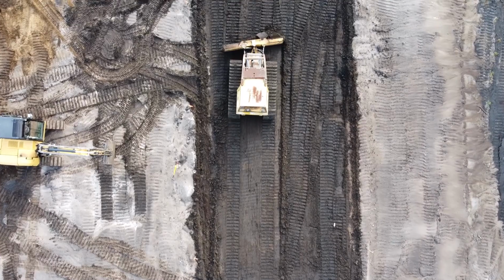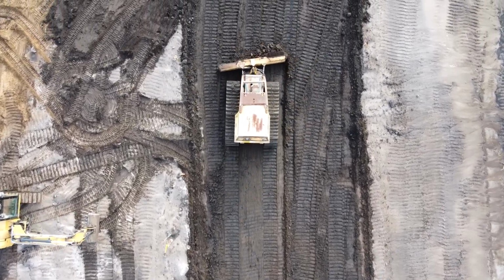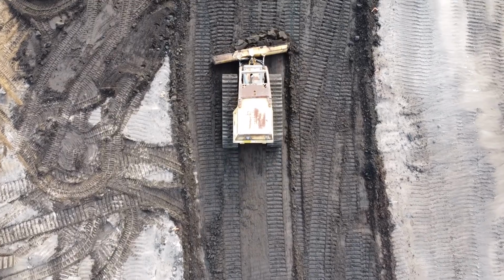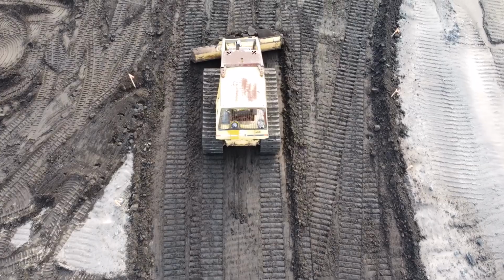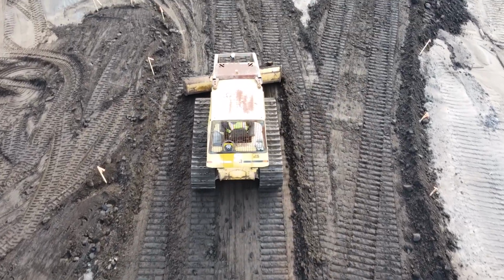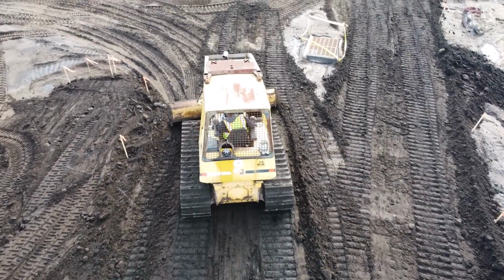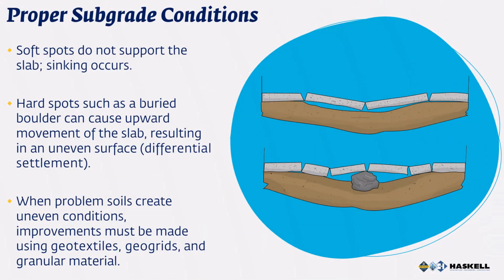The first step in subgrade preparation involves clearing vegetation, rocks, and topsoil from the construction area. Topsoil cannot be used as backfill. The site is then excavated to the established line and grade, ensuring uniform support for the concrete structure. Soft or problematic spots may need excavation, backfilling with good soil, and compaction to create a stable base. Problematic soils may require additional measures, such as reinforcing the soil with geotextiles or using a stable granular subbase made of materials like sand, gravel, or crushed rock.